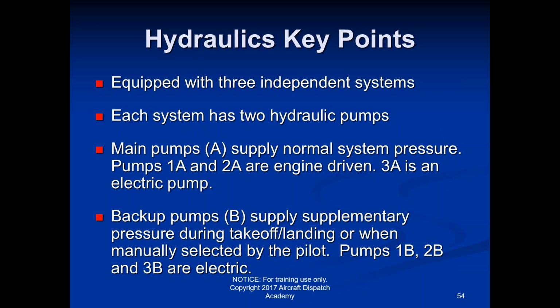So if 1A and 2A go down, would it just end up being 1B and 2B that kick on? Yeah. Now, if 1A and 2A go down, then you're probably in a whole lot more trouble than just the hydraulics going out, because in order for 1A and 2A to go out, you actually have to have the engines go out.